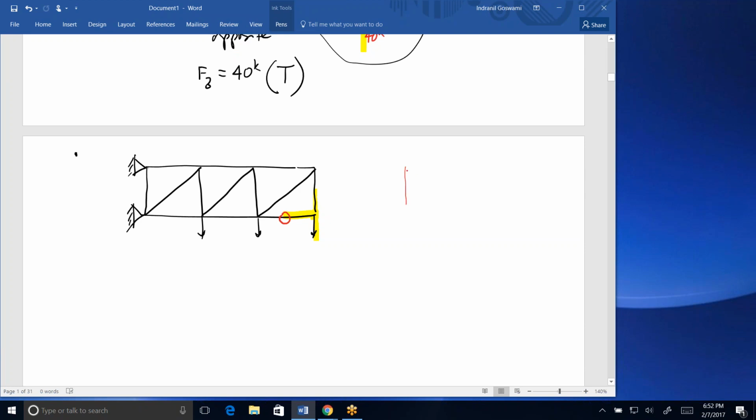So basically the structure is functioning as if there is a load hanging from here, and these two must be equal and opposite. So if this member force were, let's say, 25 kips, the force in this one would be 25 kips tension, because it would have to pull away to match this 25 pulling down. Right? So we can say this is a zero force member. And the only other one where the condition exists is this node, where you have a vertical member, a horizontal member, a vertical reaction, and a horizontal reaction, the 2 reaction forces at the pin.